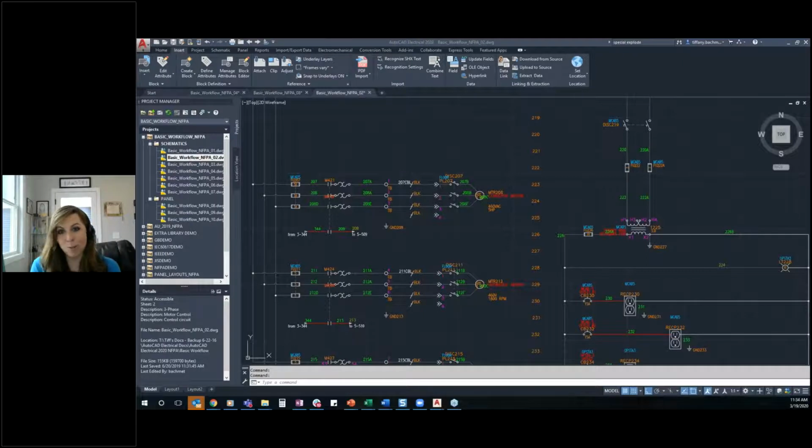I am a huge proponent of the full implementation of AutoCAD Electrical and Vault, which is vaulting all of your support files. That would include the catalog database, your symbol libraries, all of that. And you would set up your deployment of electrical to link to your C drive, to your Vault workspace area, so that it's always looking there for all of those support files. And you would automatically bring down all of those support files from the Vault to your computer.